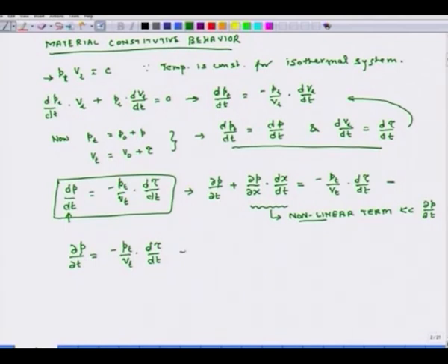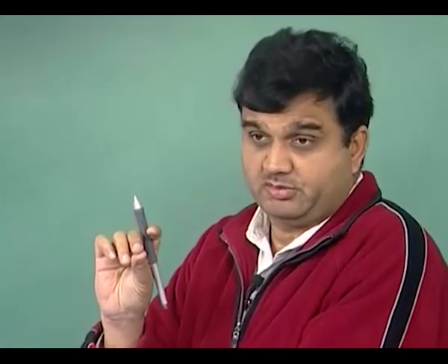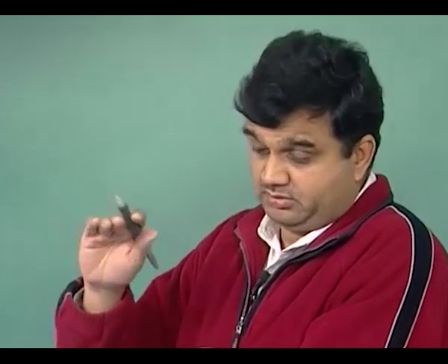And we know further that Pt is approximately equal to P naught, once again because the process of sound propagation is such that incremental pressures are extremely small compared to the ambient static pressure, which is atmospheric pressure.